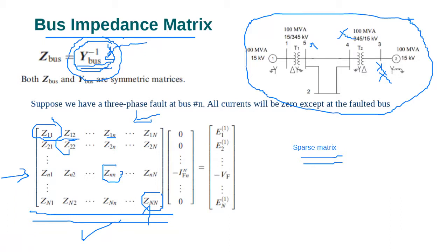You remember when we have a complex system, we have so many nodes. For example, say we have a circuit with 20 nodes, and you want to find the Thevenin impedance of each bus, or each node. You need to solve the whole matrix and get the Thevenin impedance. Here it is easy. You see now how easily we can get the Thevenin impedance of every bus.